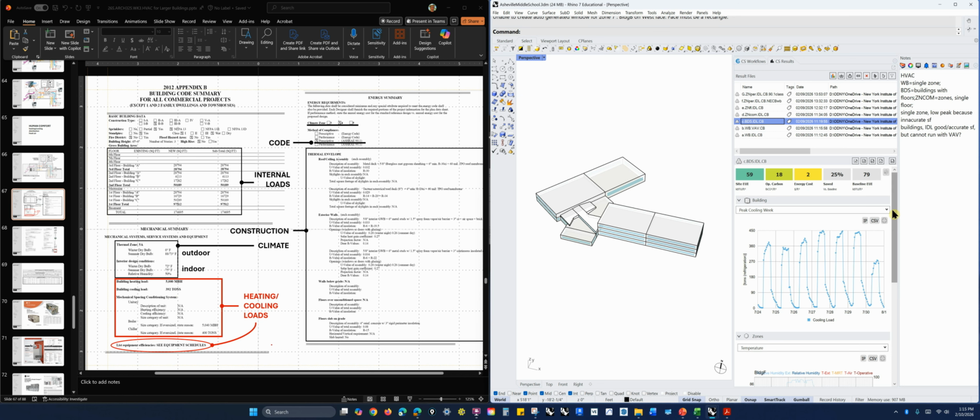And for the peak heating load, we were at 4895, where 5,000 was their peak load. So we're incredibly close. I think we kind of lucked out here because this is not a super accurate model, but it shows that by some iteration, using our common sense and what we understand, we can get closer to what the engineer who designed this found.